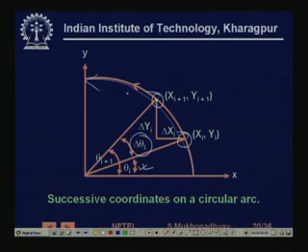One approach is to approximate the circle by straight lines, making this angle small. So you are actually traversing very short straight line segments to make the circle, and if your segment is narrow enough, you can achieve very close accuracy.